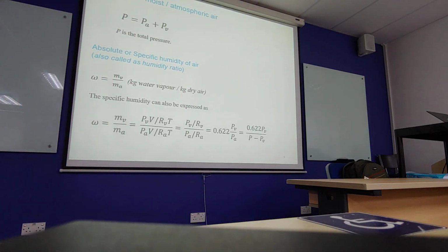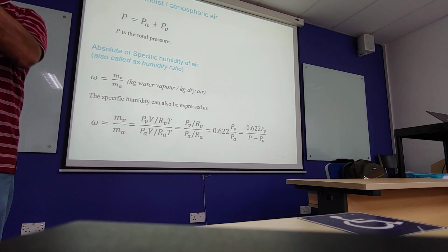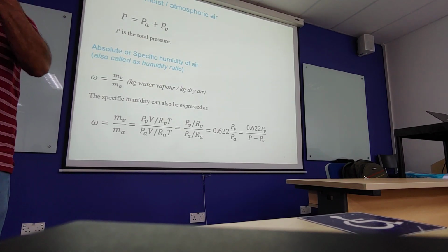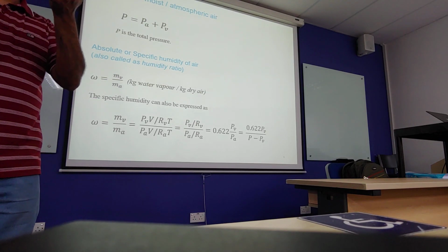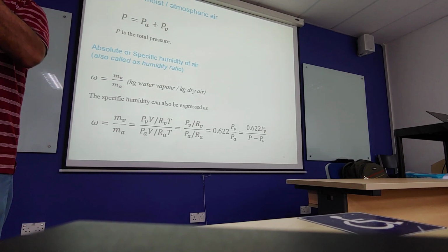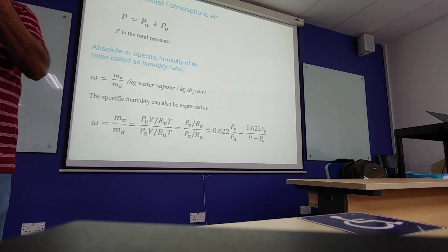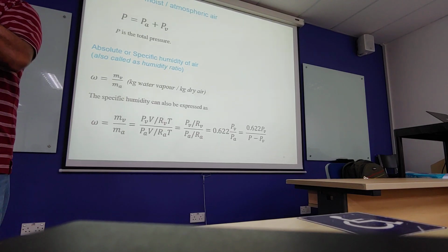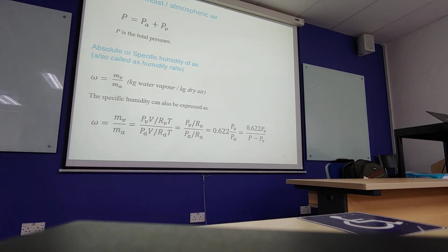Now, how would you measure a wet bulb temperature? What you do, same thermometer, you put a small piece of cotton or a face tissue paper on top of it and put a few drops of water, make it moist. So moist cotton or moist tissue paper or some kind of a cloth which will hold some moisture in it, and then leave it on the bench.